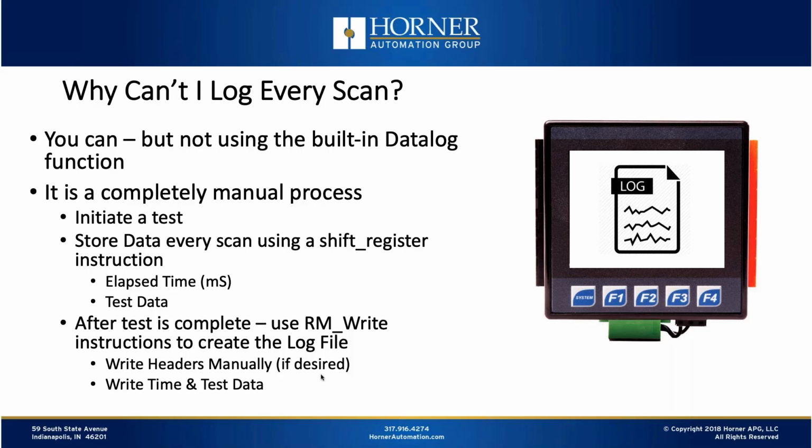Then instead of that trigger initiating a data log, it initiates some logic you write, probably utilizing a shift register, to record away the data every scan, as well as elapsed time from a millisecond-based timer, into internal registers. Keep in mind, the XL series OCSs from the XL4 on up have potentially 50,000 registers available. So a data log of 5,000 registers or something like that wouldn't be out of the realm of possibility.